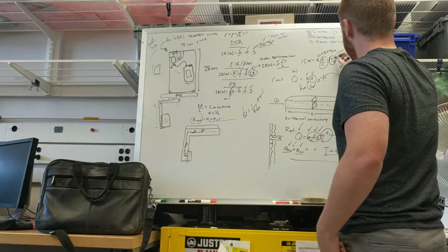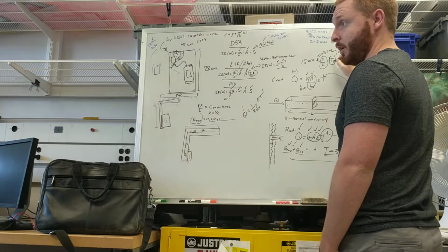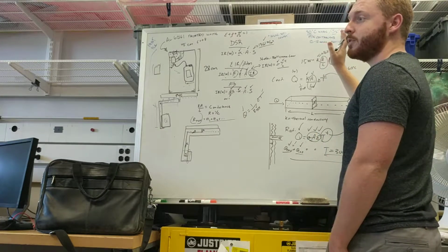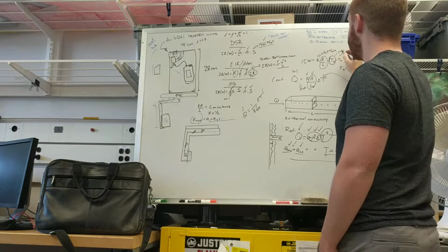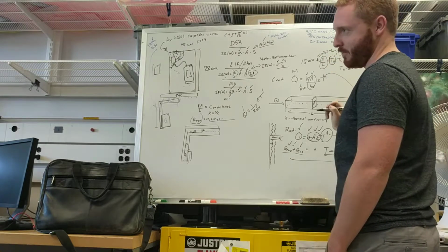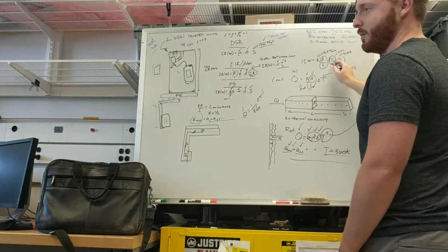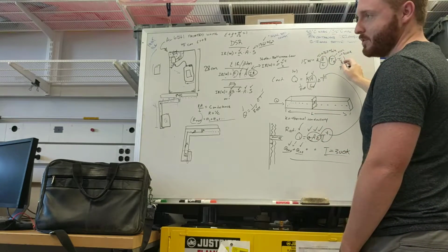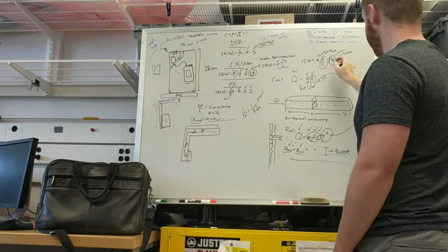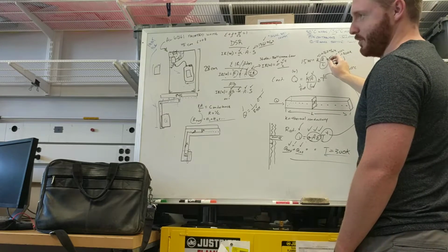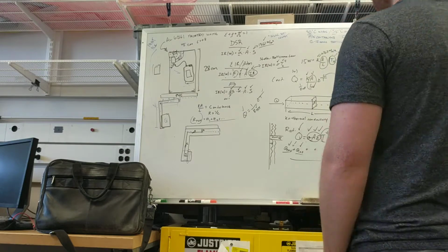You can set this to whatever you want. Let's say you want to say, I want it to be 35 degrees, just to be safe. Then you set this for 35 degrees and you figure out what the A over L has to be. So you can set the TH to whatever temperature your heart desires as long as it's warmer than TL. However, the closer you are to TL, the more difficult this is going to become.